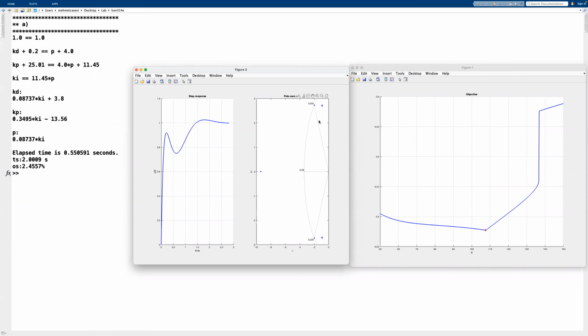Now we can see on the s-domain that the omega n value 338 was the natural frequency that we were looking for. 0.591 was the zeta value, and you can see 53.7 degrees should be this angle here. And the intersection of these two gives us the point of interest, or our complex pole pair. Then again, we have the residue pole here, which seems to be away from the dominant region, which is a good thing.